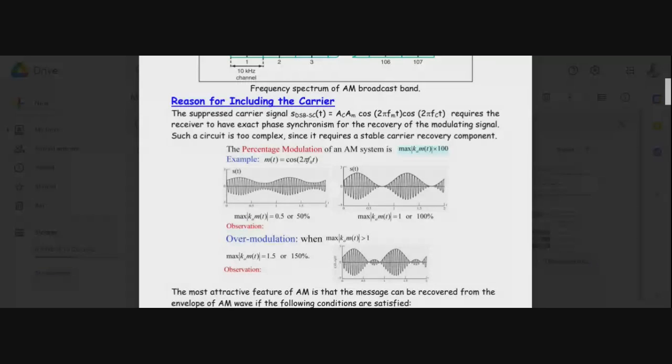So when the amplitude is down, it's not crossing the positive side. If you took a signal that just touches the peaks on the positive side, and then the signal that touches the bottom, they don't cross. That's good. That can work when you try to apply it to the so-called envelope detector that I just described below, because the envelope detector will try to follow just the outline.